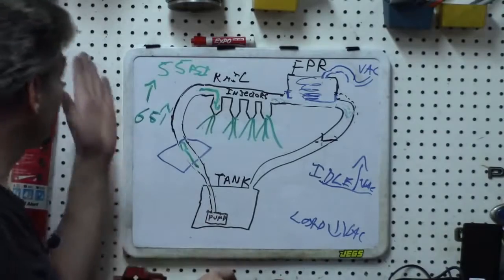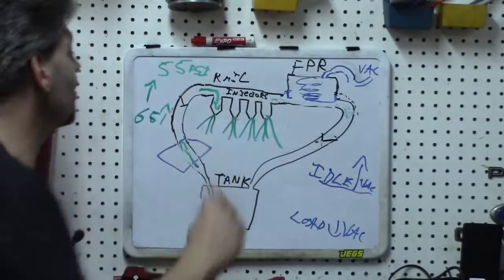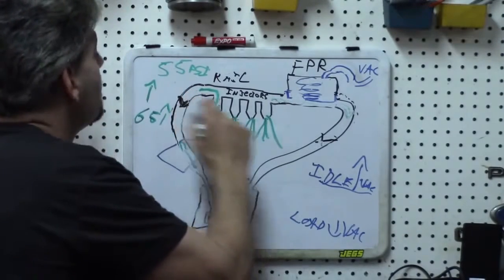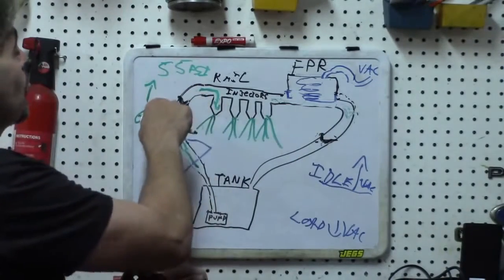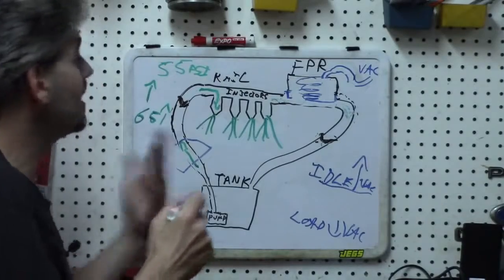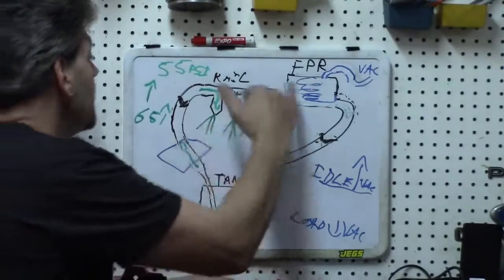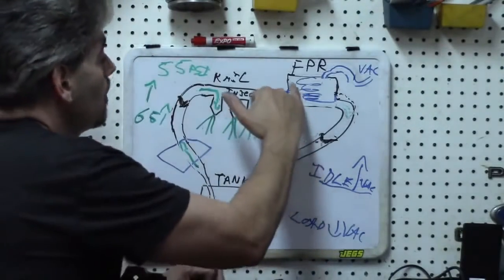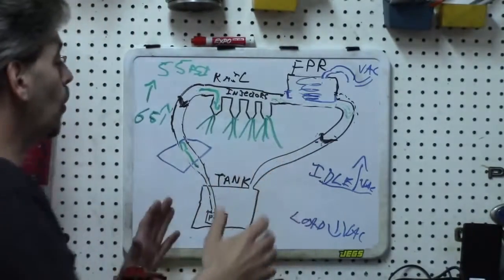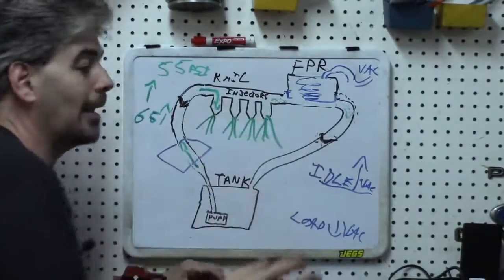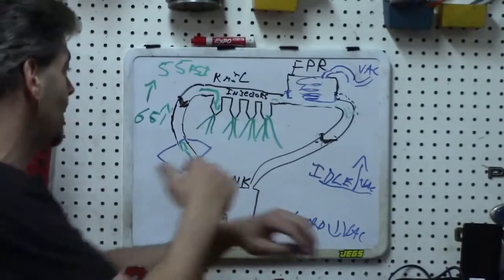Now, of course, the way to test that would be very simple. If you also pinch off the feed line, so if you block off both ends of this and you continue to drop your static fuel pressure with the engine off, then you know that you either have leakage in the injectors, leakage with the line somewhere here, or in the case of an internal regulator, you may have an internal regulator leak. Make sure, of course, again, that if you do this, that you're blocking off only on a rubber component. Don't block off, obviously, a metal line or something like that.